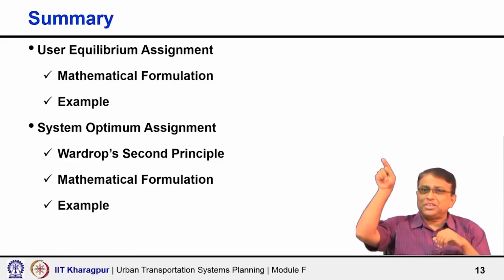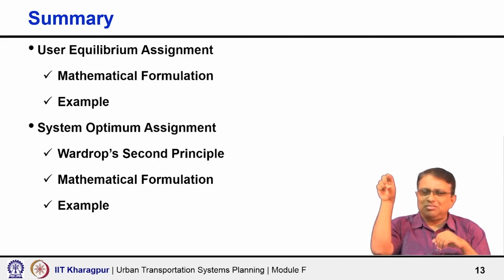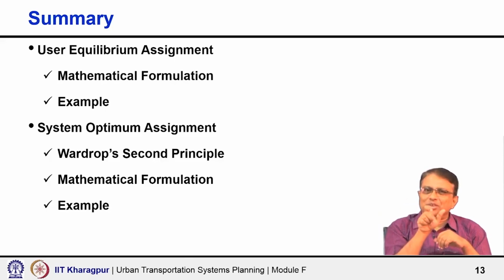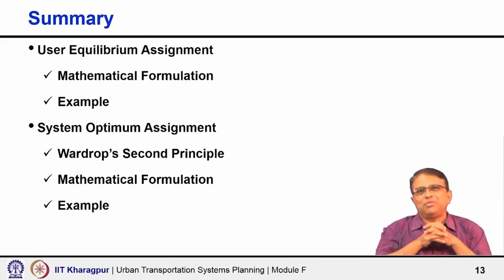Because when you are in the sharp part of the curve, then x amount of reduction in volume will give y reduction in travel time. Here on an uncongested route, x increase in the demand or the vehicle volume will not give you y increase in travel time. It will be much lesser than y, and as long as it will be lesser than y, the shift will bring the overall aggregate travel time down,